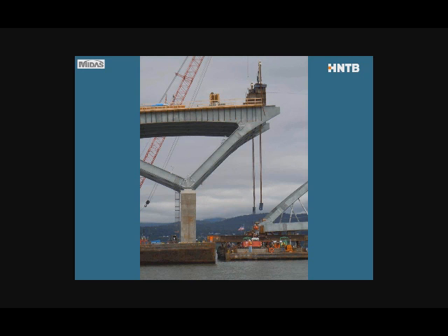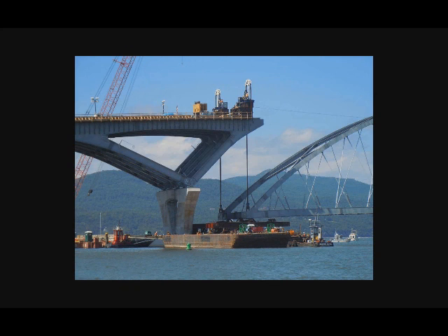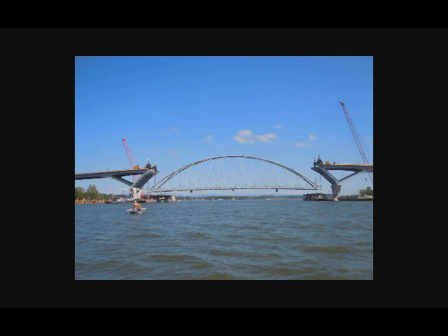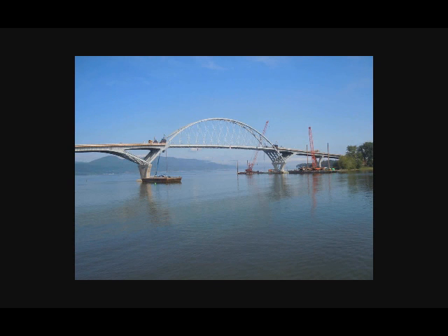So here we go. The cables are ready to be attached to the arch rib, or to the end floor beam, that is, and we have lift off. And so now the bridge is just hanging from the cables, and here it is. So the bridge is out. So in the left corner, you can see there's still a piece of floor beam underneath. So the final operation is actually to install the floor beam or the support beam that the arch actually sits on in the end.